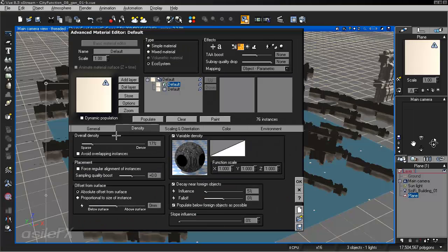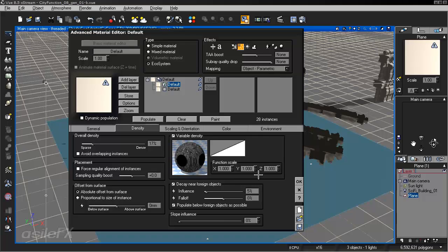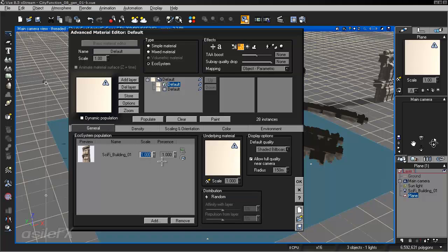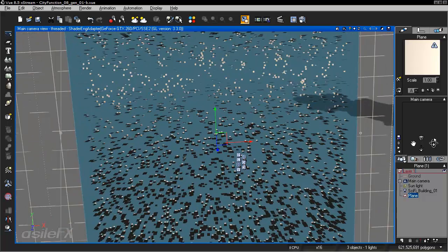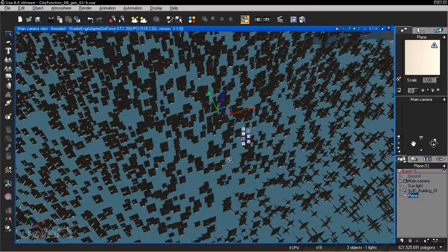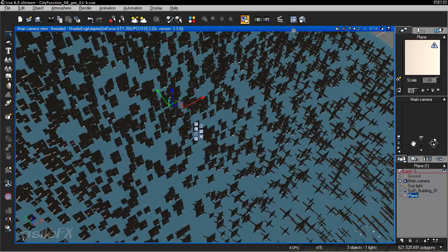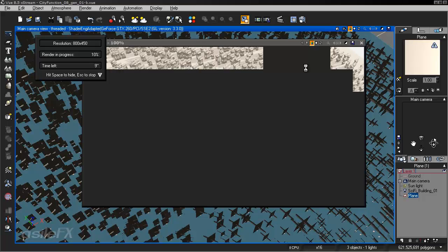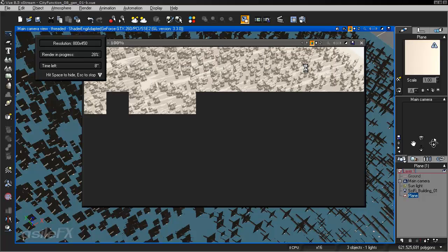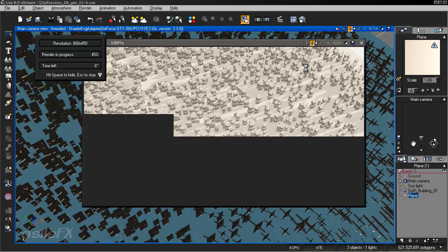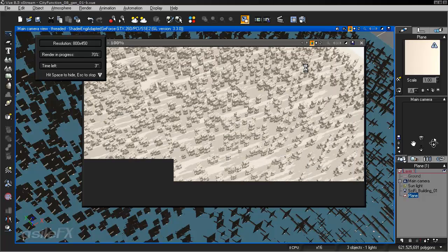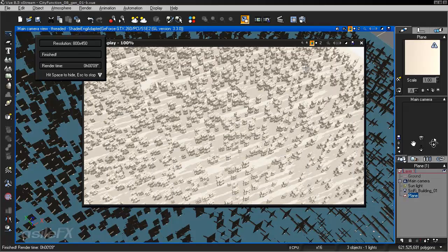So now we have that as our control. I'm going to go to the building scale, set it to 0.1, and those still might be too large to really show within that image. But you can start to see it conforming to the layout that was created from that baked or rendered image of the procedural noise.